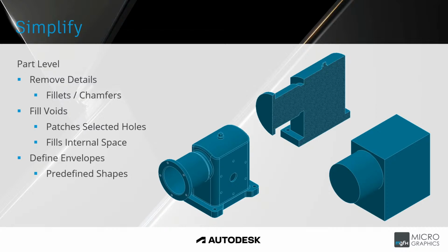You drag a box or snap a box to the correct size, and it then defines that envelope for you. So Simplify can be used at part level to simplify components down. Throughout the Simplify process, features are added to your model browser. So you have those simplified features that are added, and this can be used in conjunction with model states as well.